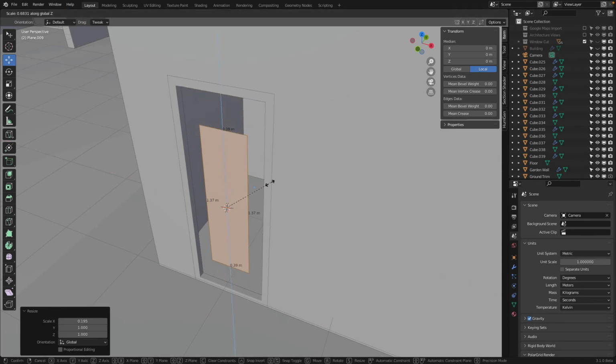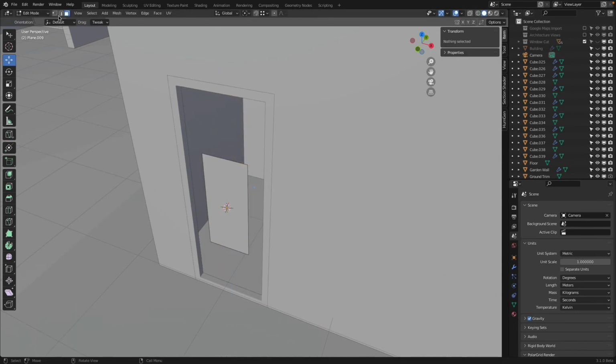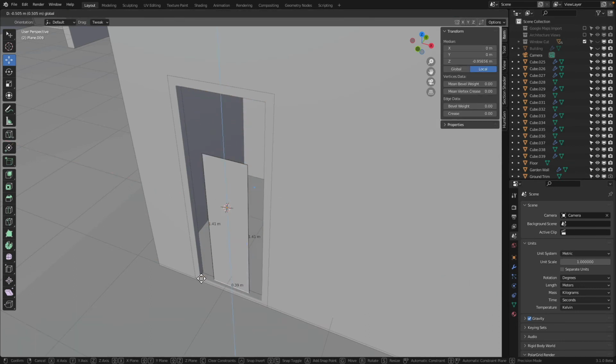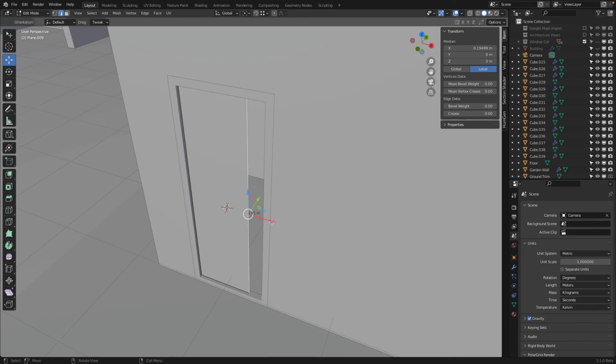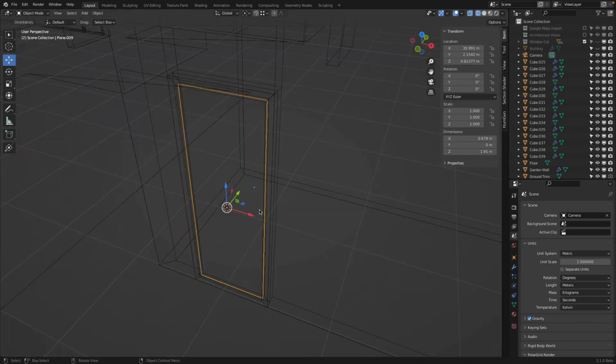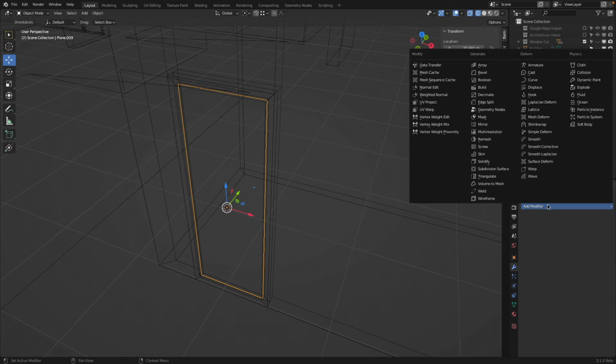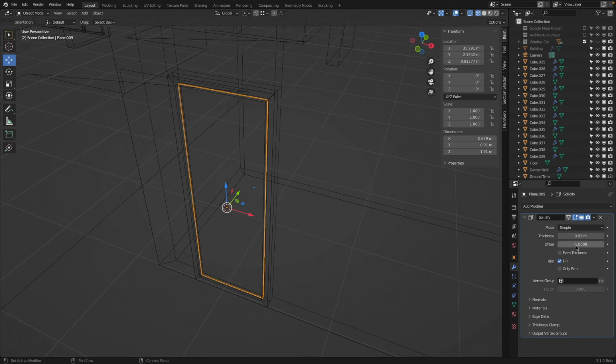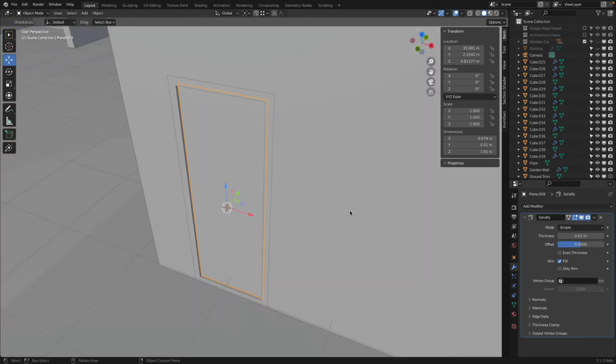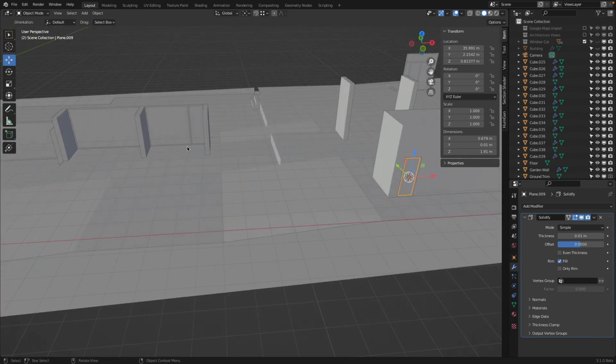SX, scale this down. SZ, scale this down. And then edge select, snap, snap, snap, snap. This is a sheet. Maybe I should have done sheet rather than the cube. And solidify modifier 0.1 centimeter there.